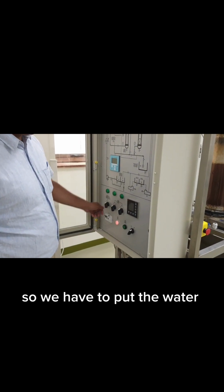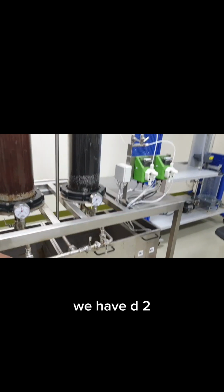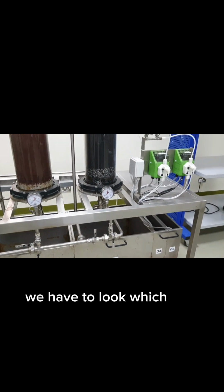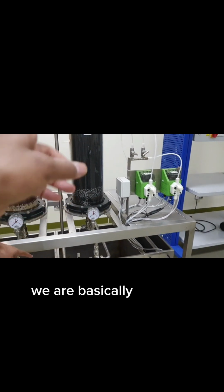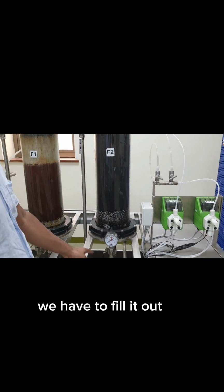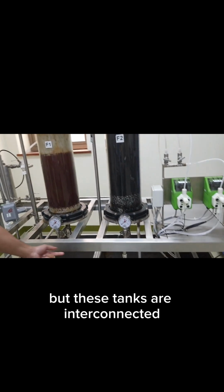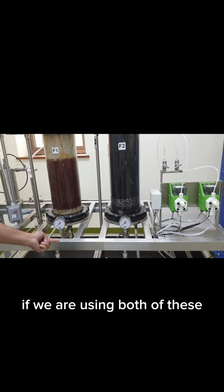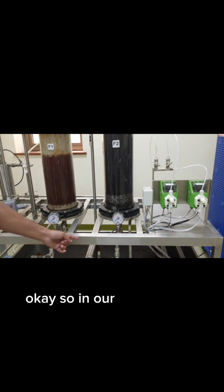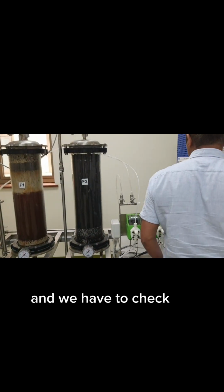So we have to put the water in the tanks. D1 or D2? We have to look at which one we are going to use. We are basically going to use the activated carbon one. If we are using this one, we have to fill this tank. But these tanks are interconnected from the bottom, so if we are using both of these, we have to fill both. In our case, we will use D2, and we have to check the back side.